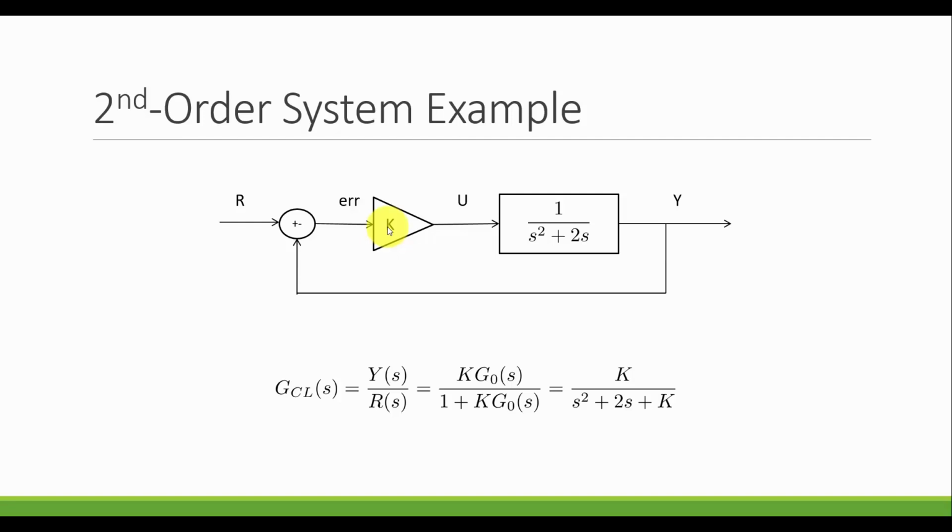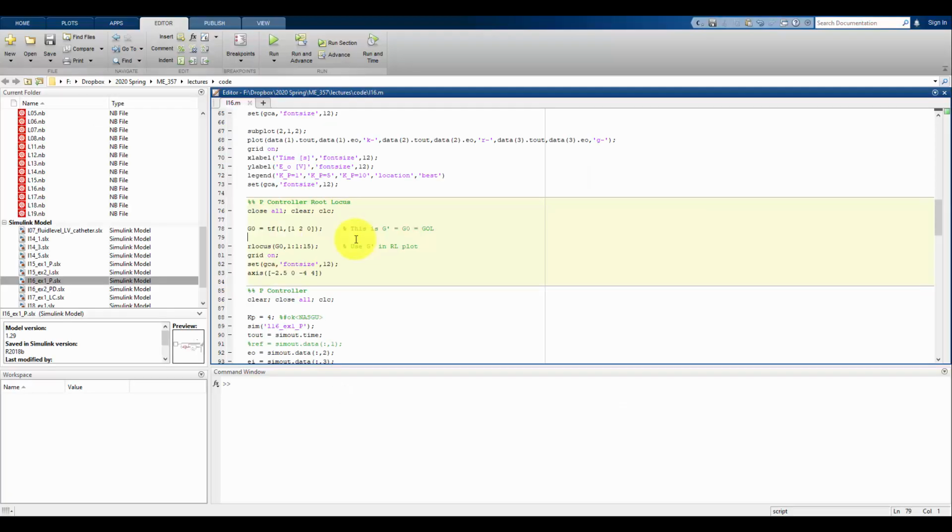Now, when we talk in the next segments about PD controllers or PID controllers, now the controller transfer function is not going to be simply 1, and we'll see what it looks like then. But for this P controller, yes, the controller is simply 1 until we choose K. So I'm doing the root locus on G0, which is, again, just 1 times G0.